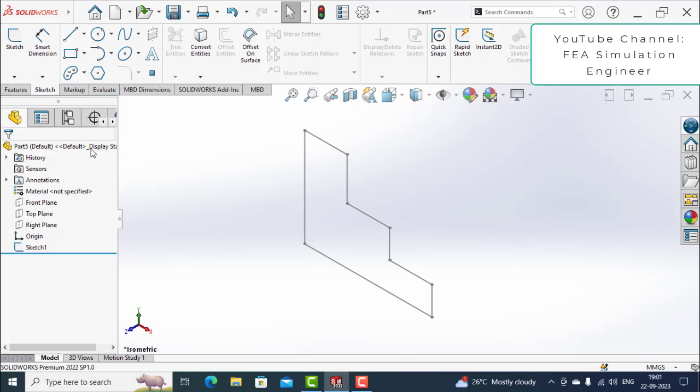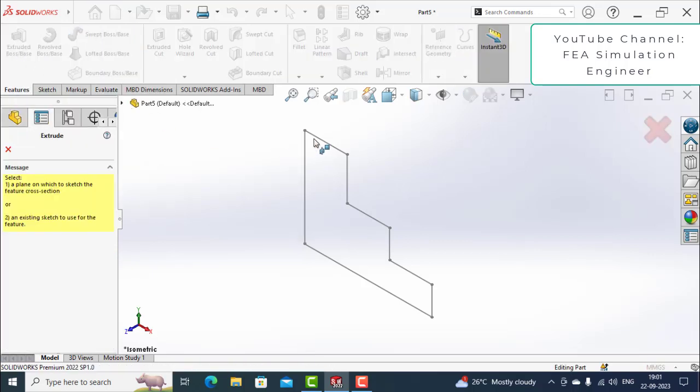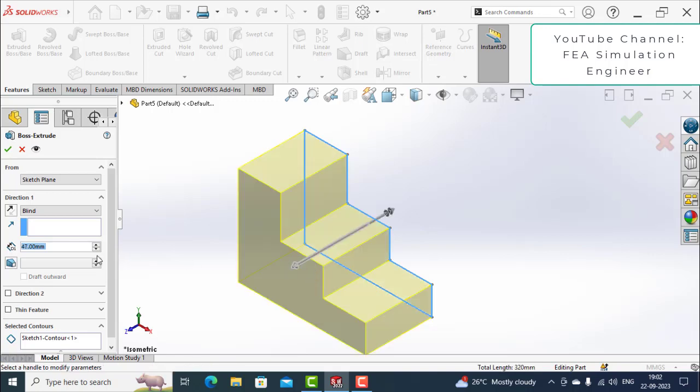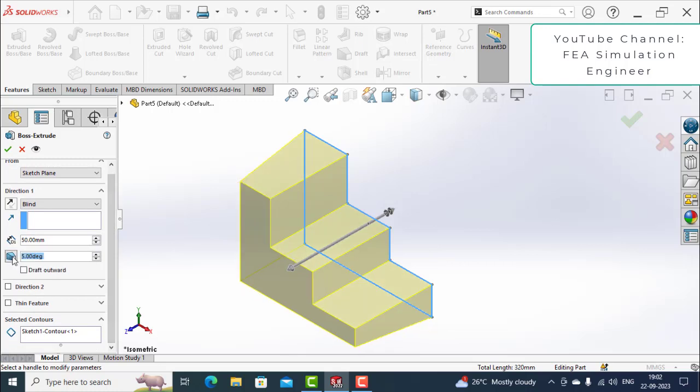Go to features, click extrude and select the loop. Carefully observe that the material is adding perpendicular to the sketch. The total depth can be adjusted here. While extruding itself, we can give some angle or draft. See, now the surface is not straight, it is extruding with some angle.